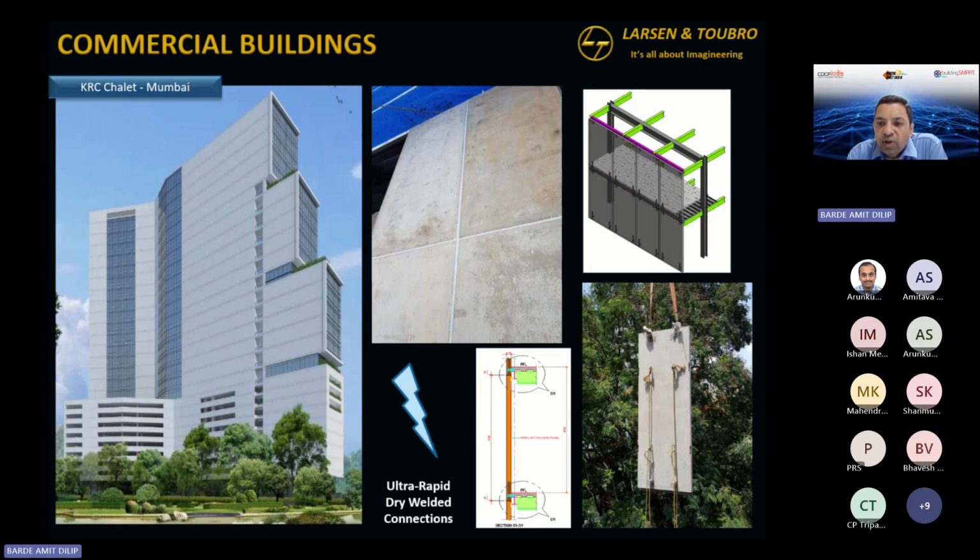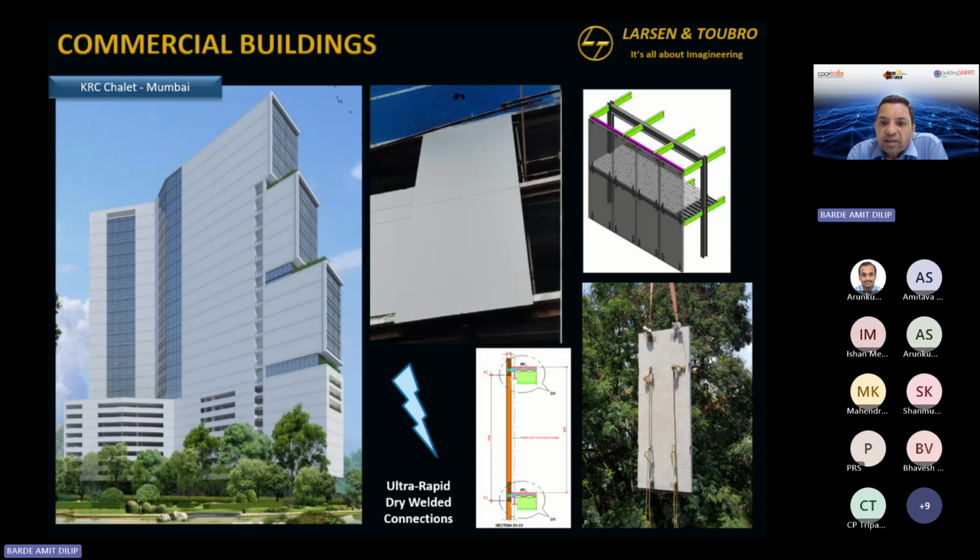Facade, I mentioned, we are slowly looking at even pre-painted facades where site activities can be reduced further. So this is a steel structure attached to the building from outside, with welded connections in precast embeds, with the option of painted panels itself.